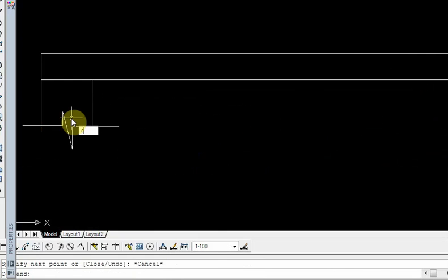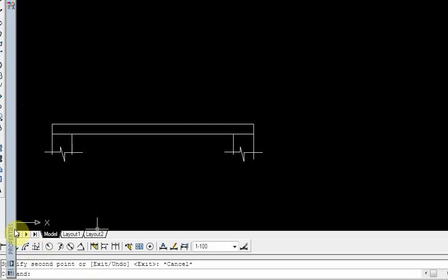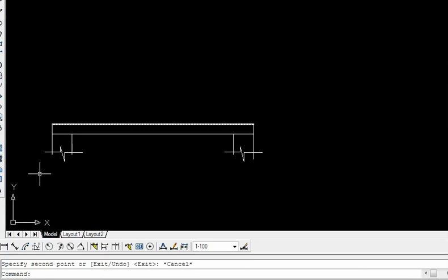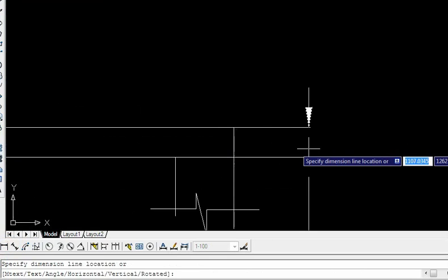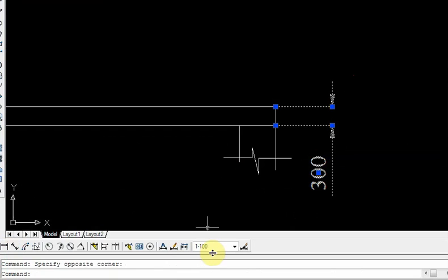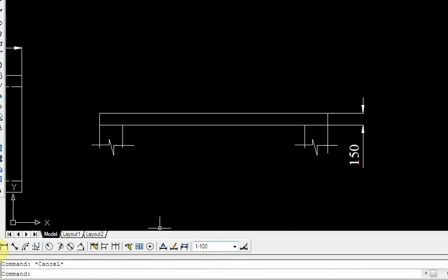So we can see we are showing the section in the shorter direction. I am showing the dimensions here, how we get them. We can write the dimensions here also. I will show you how we can write. The thickness of the slab is given as 150. Let us take the scale as 1:50. We can see the thickness is 150 here.